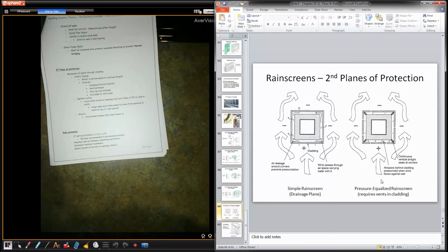That could be a good thing. So sometimes having a vented cladding system is good because it will take any moisture out of there and pull it out. What you don't want to have happen is all that moisture go into an attic. So here you can see two spots on the wall where air can flow out horizontally as opposed to going from the top up. So one spot actually just kind of neutralizes the moisture, so it's kind of stuck there. Two spots allows it to flow and get out. Okay.